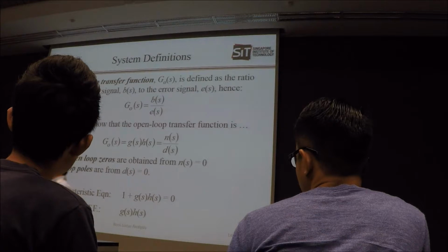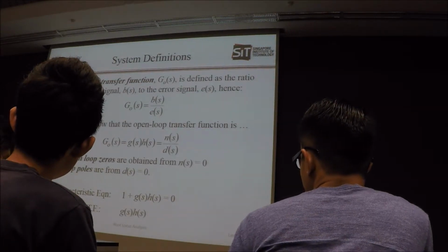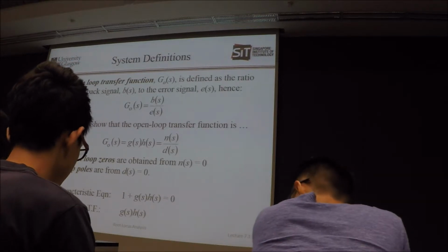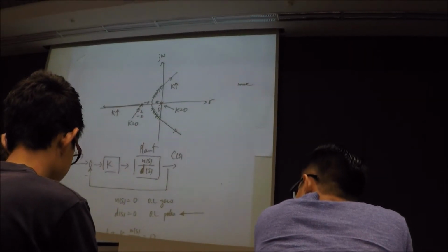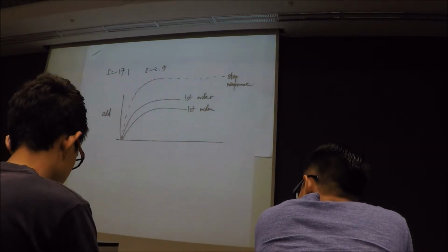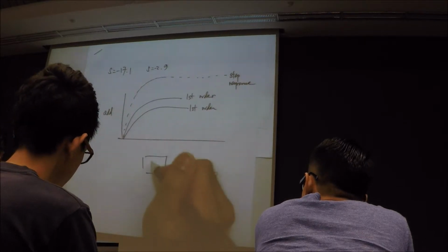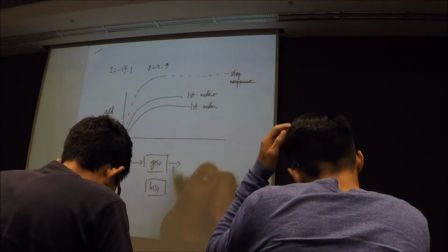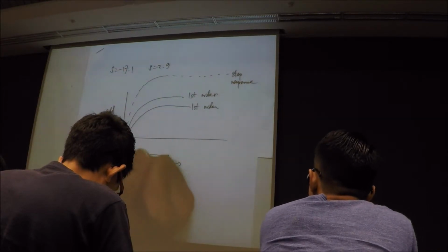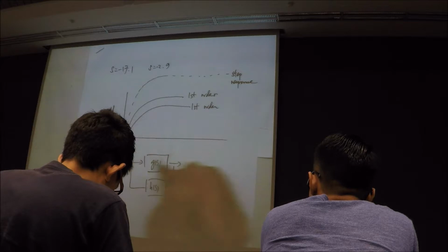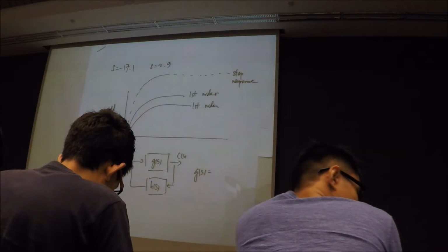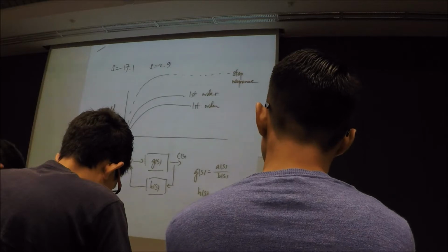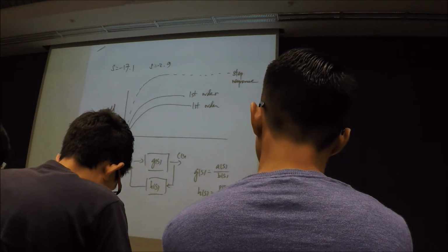You combine the two together because you have your G(s)H(s); it depends on your G(s)H(s). If you remember the last round I showed you, the information given by the lecture materials is a little bit not quite accurate. Here, this is your G(s), and this is your H(s). So last round I showed you that G(s) can be broken down into A(s) over B(s), and H(s) is going to be equal to P(s) over Q(s).